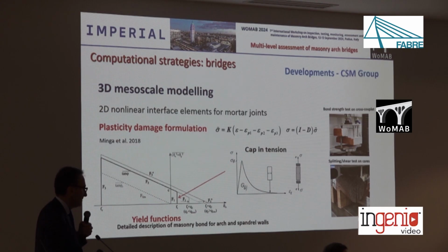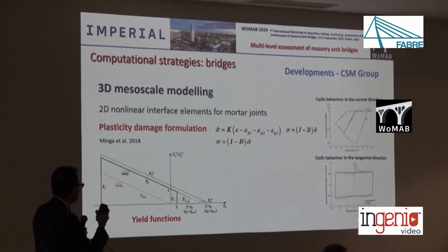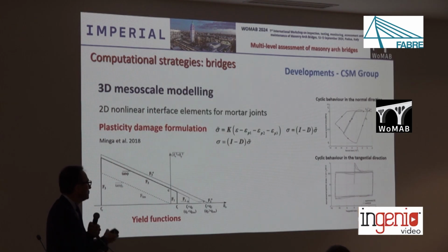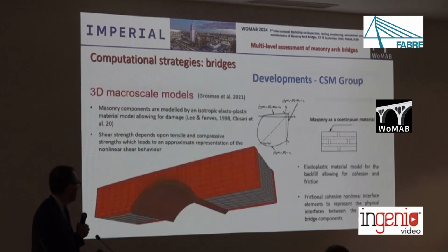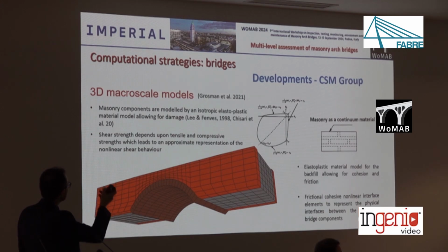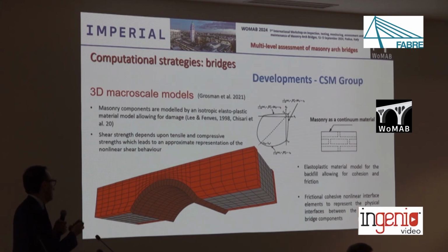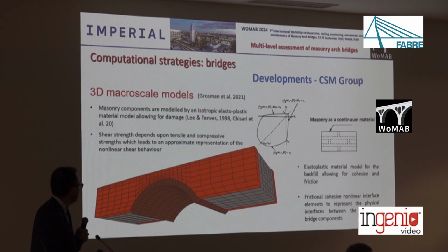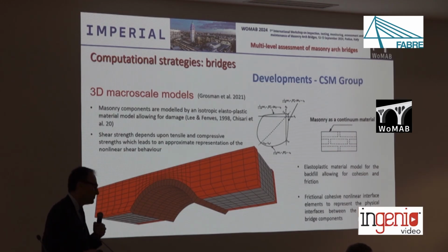Nonlinear interfaces enable separation and shear sliding. The characterization at the strength level can be achieved via simple material tests. Our interface material models also take into account opening and closing of cracking and the plastic frictional behavior under monotonic loading conditions. The counterpart we developed, and are using today to showcase the potential of the method, is a more standard macroscale approach. Of course, it's more efficient.